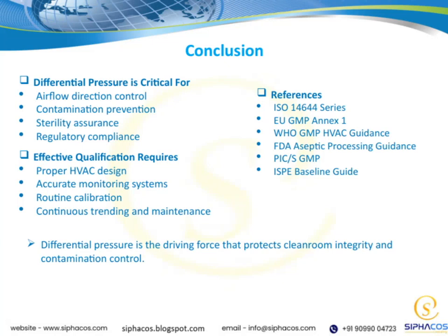Differential pressure is the unseen force that keeps cleanrooms safe and contamination at bay. It controls airflow direction, prevents unwanted particles, and helps ensure sterility, all crucial for meeting strict regulations. To qualify these systems effectively, we need well-designed HVAC setups, precise monitoring, regular calibration, and ongoing maintenance. Together, these elements create a reliable environment that meets global standards and protects product quality.